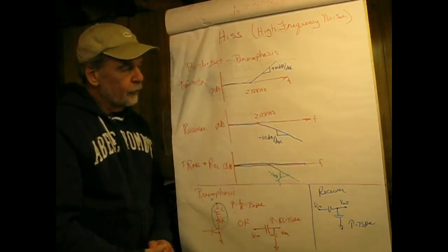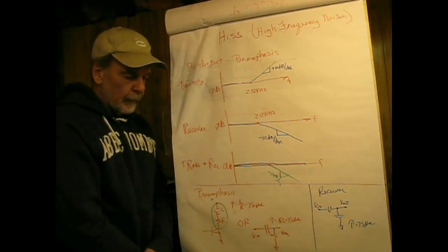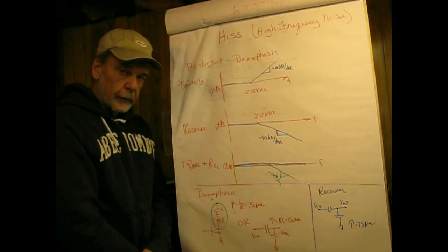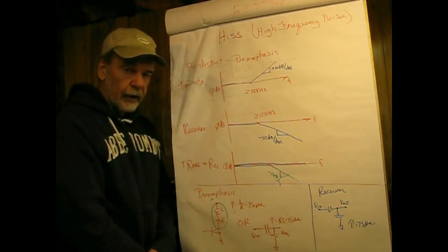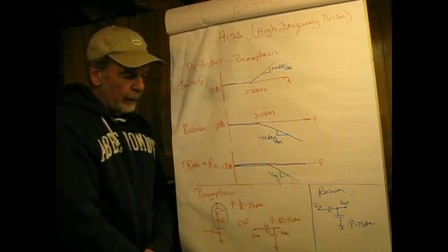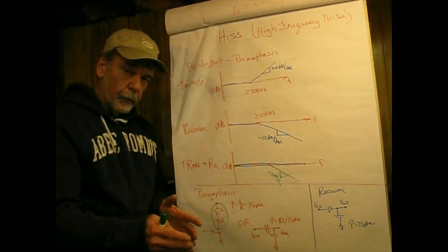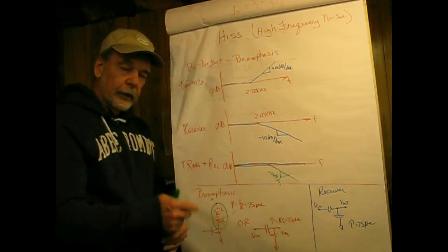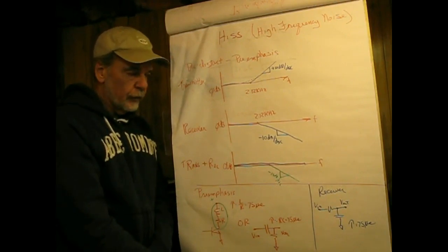Now the same thing is done when you speak out of your local exchange. On your regular telephone line, your voice is compressed, and that makes an 8-bit system look like 10.5 bits. When it gets to the receiving central office of the person you're talking to, it's uncompressed to make it almost the same as it was when it started out.